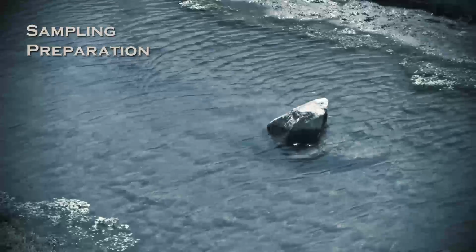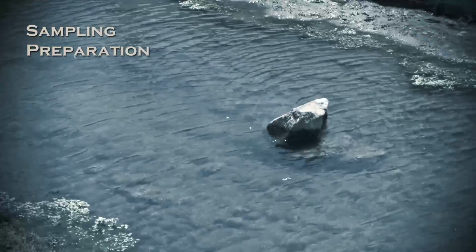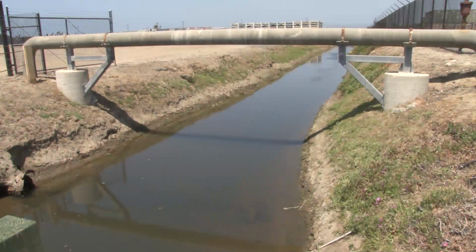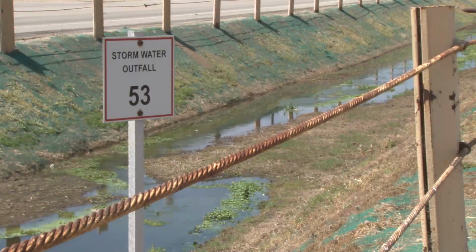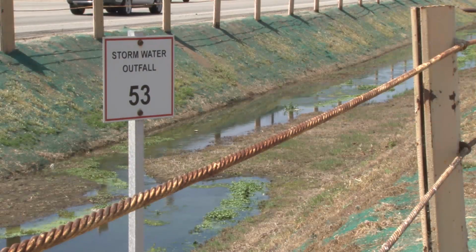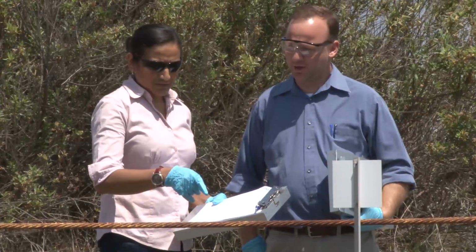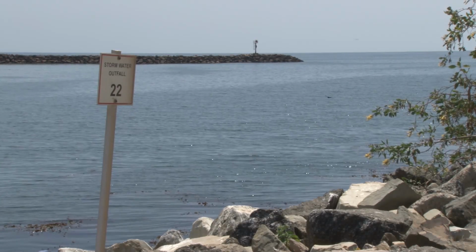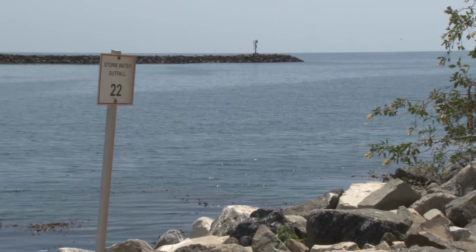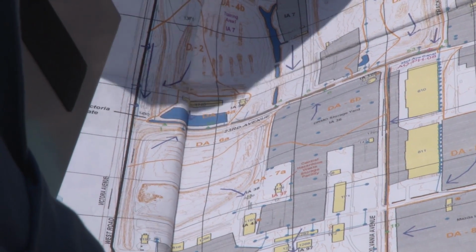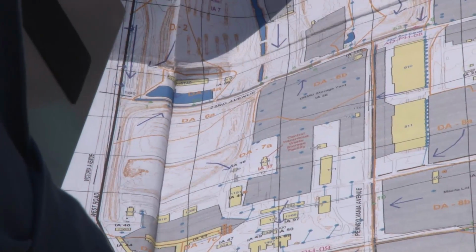Prior to the sampling event, the sampling team will select a sampling location. The sampling point must be representative of the entire discharge. Some facilities already have their sampling locations identified. Be sure to evaluate sampling locations against the SAP as guidance. This may mean sampling more than one outfall or discharge per facility. You must also become familiar with routes to and from the sampling location.